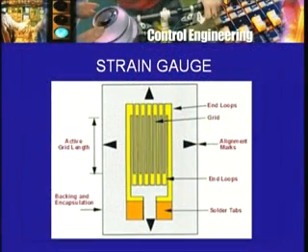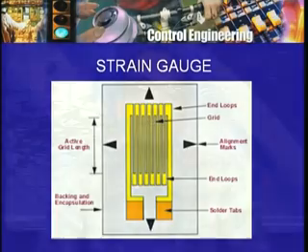By using things like strain gauges and so forth, this twist can be converted into a voltage finally as usual, and therefore the motor torque, or the torque at that section of the shaft, can be measured. But it's not so easy. It's not as easy as measuring the speed of the shaft simply by having a tacho generator and looking at its output.